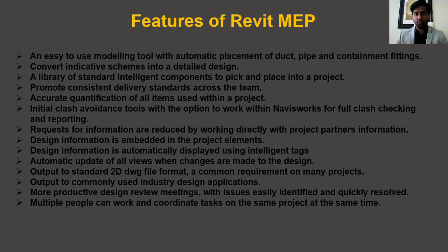So this is a very big issue which affects the time and even the cost of the project. To avoid that, Revit provides you with the work sharing option, which enables you to work together in a single network system, or even using the cloud system of Autodesk, which is BIM 360, which enables you to work together in a coordinated way in the same file, so that whatever changes happen in the architecture or any other discipline, you will be able to see the changes right away. So that is what we have here. Multiple people can work and coordinate on the same project at the same time using the work sharing option, which is in the Revit software.